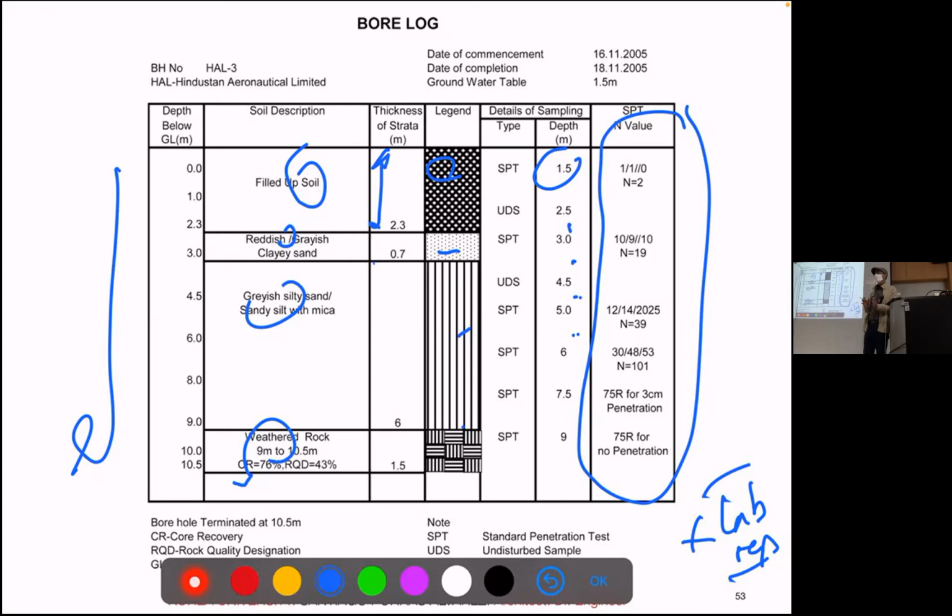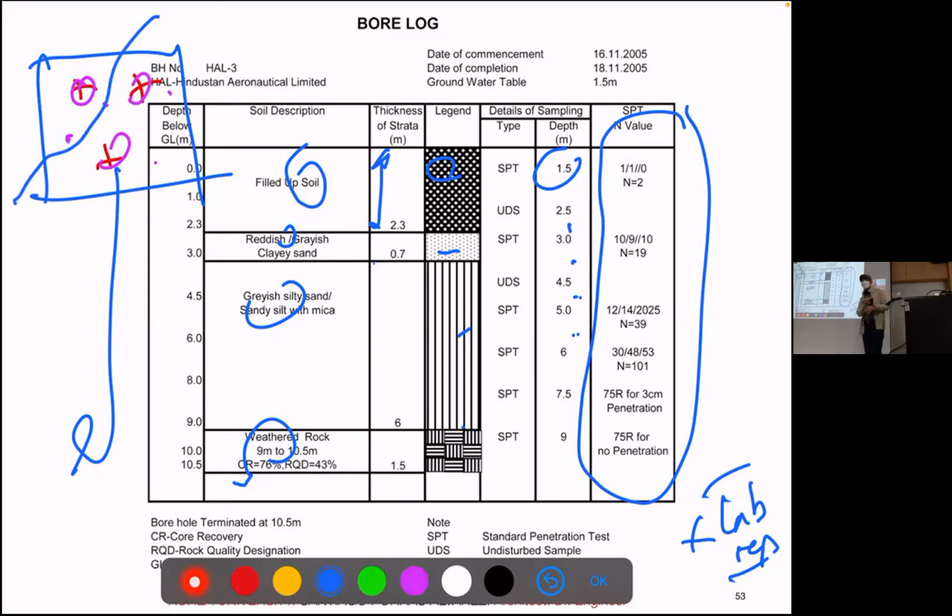So you get a lot of information. What do we do usually? If we have a big plot, we try to plan 3 points which we think are critical for this survey, and then additional small points with the standard penetration test, to see if there is anything special. Because sometimes we are unlucky, and those 3 are totally perfect, and we have an underground river just between them. That happened to me once.